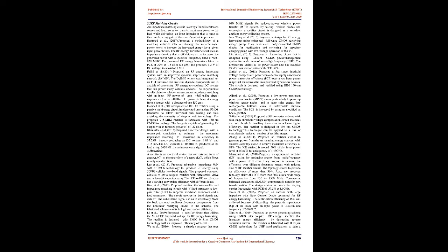Cao et al., 2019, proposed an RF energy harvesting, RFEH, scheme that uses a tightly coupled electromagnetic resonance technology. A relay resonator placed in the middle of the tag antenna and the reader increases the PCE of the module. The relay resonator design considers the coupling concept of the resonant technique and near-field magnetic field.